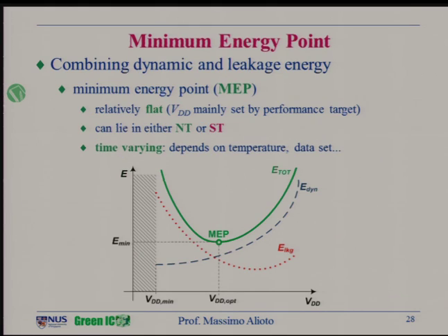Okay, let's put everything together. So we have dynamic energy here, leakage energy here. So the overall energy has this green trend. So we have a minimum energy point, interesting, which is typically pretty flat, and it can also lie either in near threshold or sub-threshold.